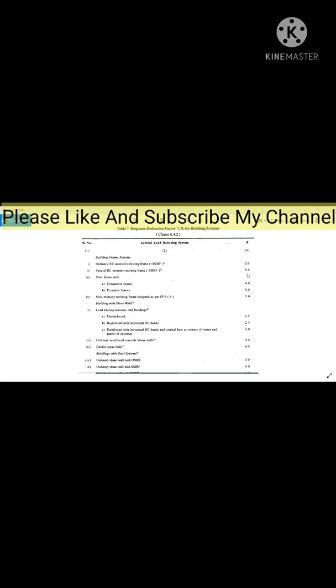They have categorized it as an ordinary or special one. If you are using a good quality or higher grade of concrete, then you can consider it as an SMRF, that is, special moment resisting frame. And if it is ordinary concrete, you can call it an OMRF, that is, ordinary moment resisting frame.